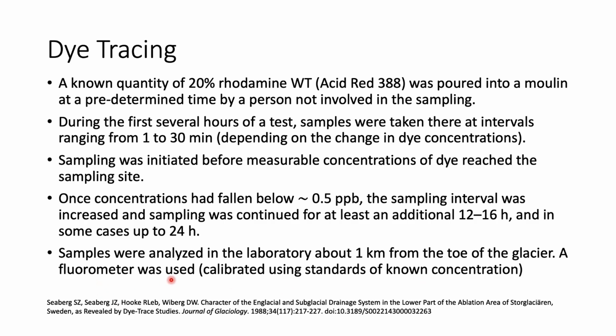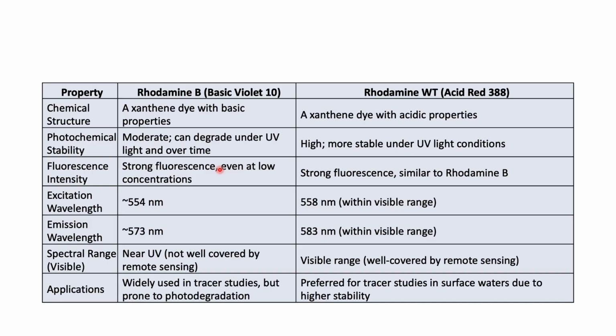A fluorometer was used. Basically, they calibrated using standards of known concentration. So this is how the dye tracing actually starts. Then let us look at what this rhodamine WT is, which was used. There are two major rhodamines which are used for studying colorimetrically.